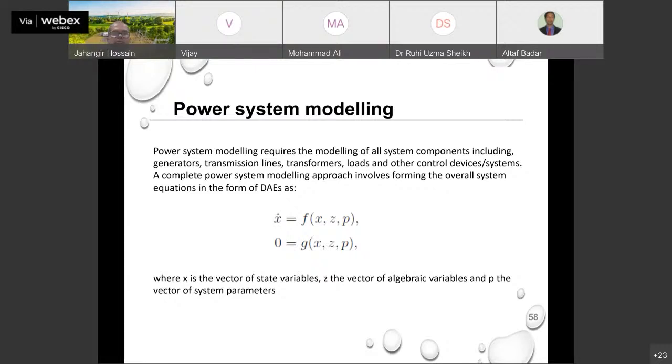So if you would like to use artificial intelligence, what do you need? You need your historical data. That historical data, for example, is what data you got when it was grid connected. It could be, as I said, either voltage, frequency, or power. And then you also need some data for the islanded condition as well, and that's how you can train your system, and that's how you could utilize those historical data. Based on that, you can analyze and identify the islanded condition.